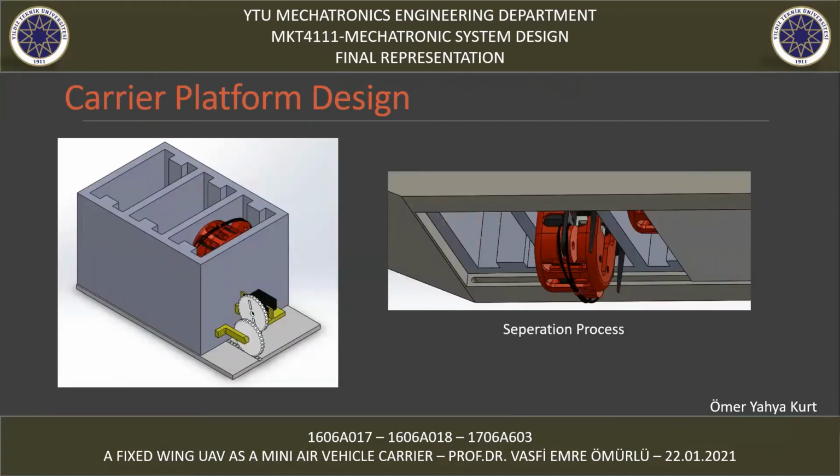A triple capsule has been designed for easy storage of the designed drone. Circular motion of the servo motor is transformed into linear motion with a gear design that includes a pinion gear. With every 60 degrees of movement of the servo, a drone leaves the aircraft. The cover will move on a rail.